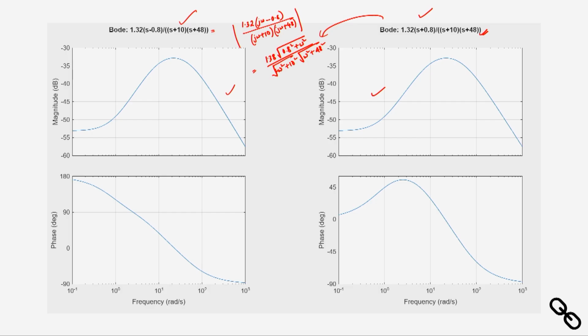In the previous example, I assumed that there are no zeros on the right half plane, so I said that this is the correct transfer function, but it might not be so. In that case, you have to go to the phase plot. First find the transfer function of the system considering that the system is minimum phase, so there are no poles and no zeros on the right hand side. Once you have that transfer function, to be sure that it is correct, you check the measurement of the phase. How is the phase looking?